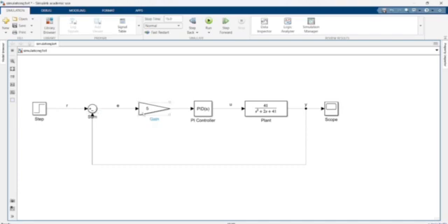After that, for the gain, a constant value is multiplied with the input by the gain block. Each of the input and gain variables may be a scalar, vector, or matrix. In the gain parameter, we can define the gain value. Element-wise or matrix multiplication can be specified using the multiplication option.